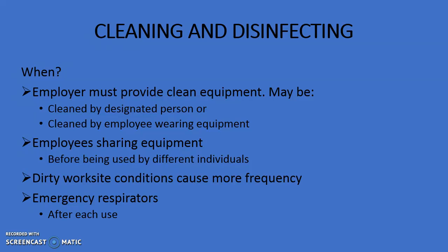If the respirator is being worn exclusively by an individual employee, the equipment must be cleaned and disinfected as often as necessary to be maintained in clean and sanitary condition. Respirators used in fit testing and training shall be cleaned and disinfected after each use. Worksite conditions also determine the cleaning frequency. Working in a dirty environment will require that the respirator facepiece be cleaned more frequently. Emergency use respirators must be cleaned and disinfected after each use.